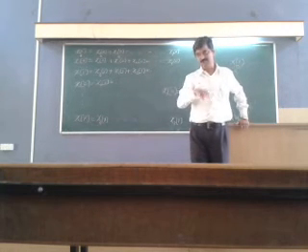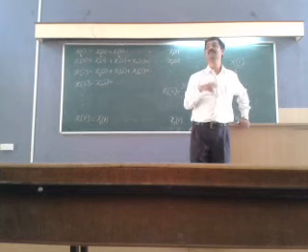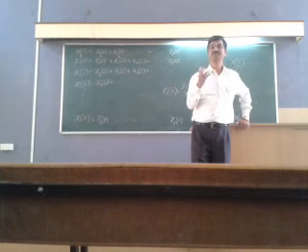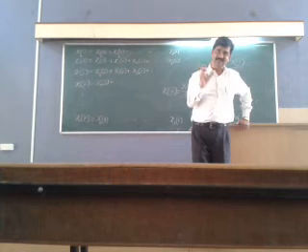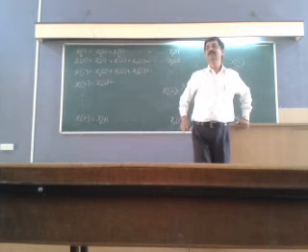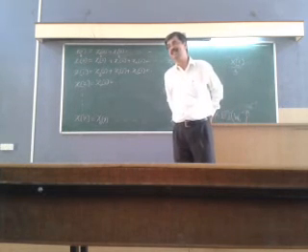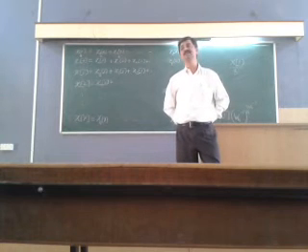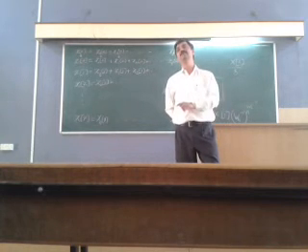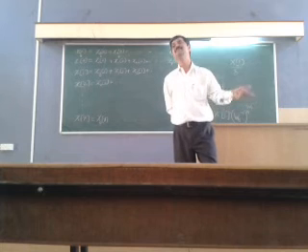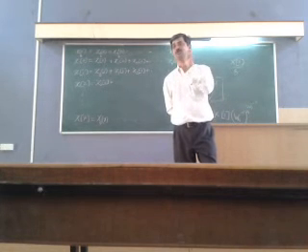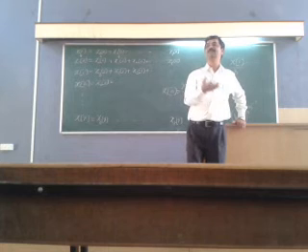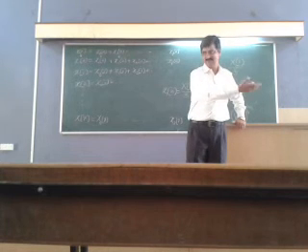And when n changes, the phasor will move by an angle of pi by 4. So capital X1 upon 8 is the initial position of the phasor. When I say initial position of the phasor, it includes the amplitude as well as the phase at 0. So if x1 is real, in that case it will give you only amplitude, because phase at 0 is 0.